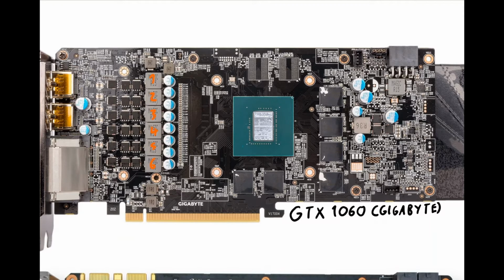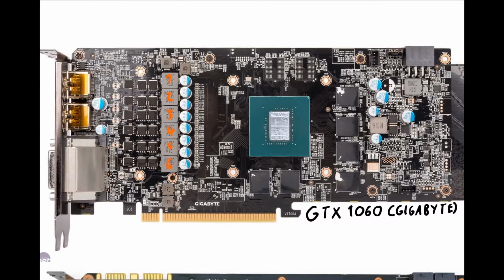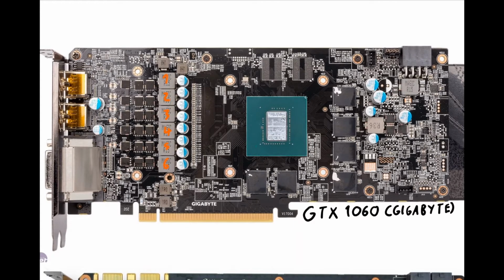So the fact that we don't see any doublers, and sadly we can't see the PWM controller, which would give us a definitive answer of how many phases these actually are. Because what is also possible is that this card could have a PWM controller with only 3 phases. Imagine the PWM controller would be here, and it gives out 3 PWM signals. What could also be possible is the PWM signal just goes into 2 phases. That is also possible, and that would be what I call a big 6 phase. That is possible.